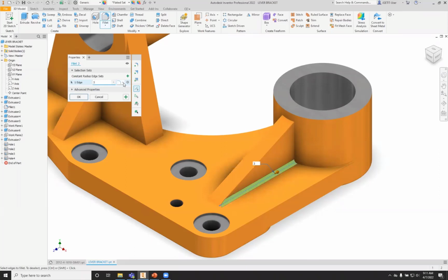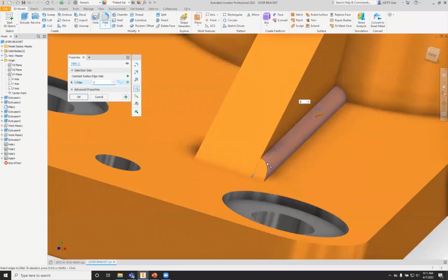Another option that we have is the type of fillet that we're going to create. Whether it's a tangent fillet, which is your typical basic fillet, or G2 smooth, which for this particular case you won't see a whole lot of difference, but it's the way that your fillet blends between the two surfaces that it's going between. And then the other one, which is rather interesting, is an inverted fillet. This is a rather powerful option to create an inverse fillet, something where maybe in the past you would have had to do a sweep to create this inverted style instead of the concave way of creating a fillet. Depending on what your design requires, this might save you some time when you need to create this type of feature. So we'll take this back to a tangent.